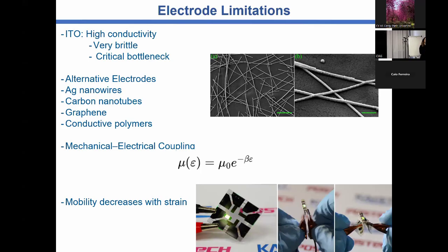So if you want to apply, for instance, in that roll-to-roll machine, the ITO is not suitable. So we must just switch to another oxide, even though we use a semiconductor based on organic materials. The electrodes and transparent electrode, they have this limitation. So if you have flexibility on the semiconductor and don't have it on the electrode, it doesn't matter if the organics are flexible.